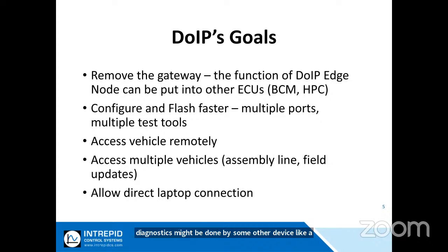There's a lot of legwork we have to do just to avoid colliding with other diagnostics that might be happening on the bus. But with DoIP, I can have multiple concurrent connections all doing diagnostics all at the same time. So I could actually open up multiple connections, flash multiple ECUs, or open up multiple connections, get the information I want, etc.